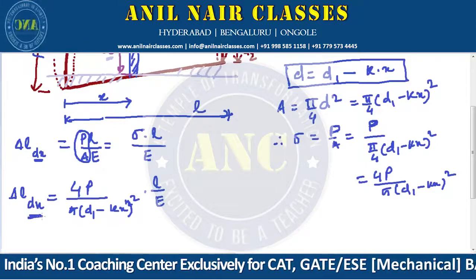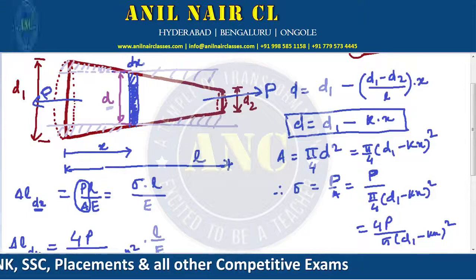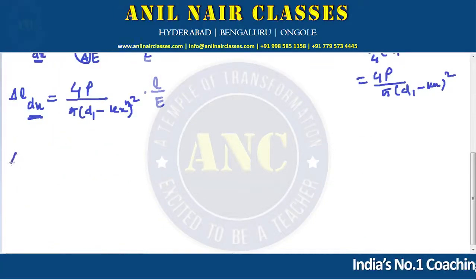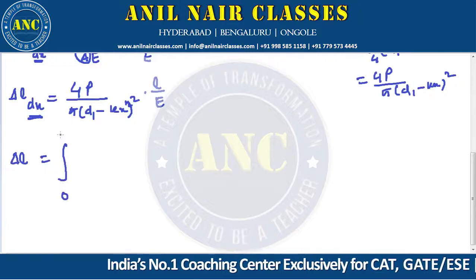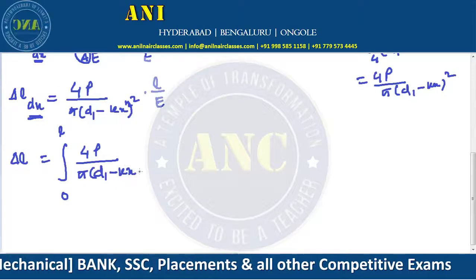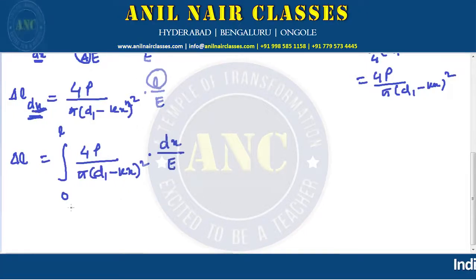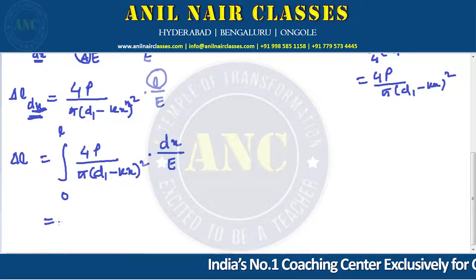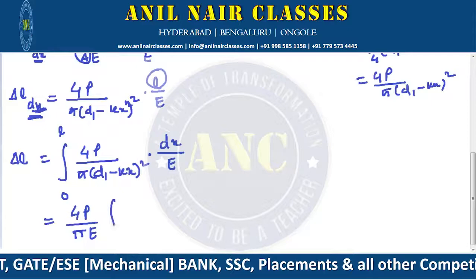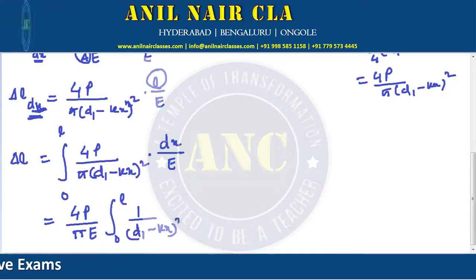Now this is the change in length for this particular dx. But we are concerned with the whole tapered section, that is for length L. Therefore we will find the total change, which is the integral from 0 to L of this section dx by E. We take the constants out. The constants are 4P by pi E, times the integral from 0 to L of 1 by (d1 minus kx) square into dx.